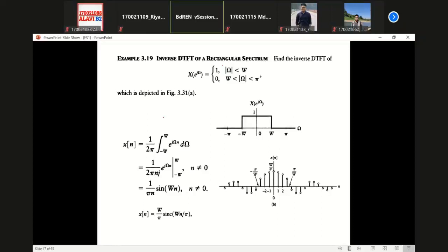That means if we have a discrete pulse, again I am rewriting it, something like this, then your Fourier transform will be something like this, okay? That means a sinc-type function in the frequency domain. This axis is capital omega. This is your n. That means a pulse in your time domain, of course discrete, is generating a Fourier transform that is a sinc-like function in the frequency domain. And most of the energy is contained within the main lobe.